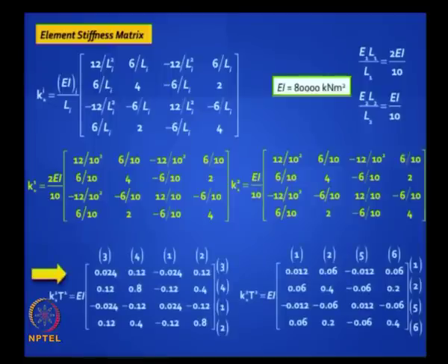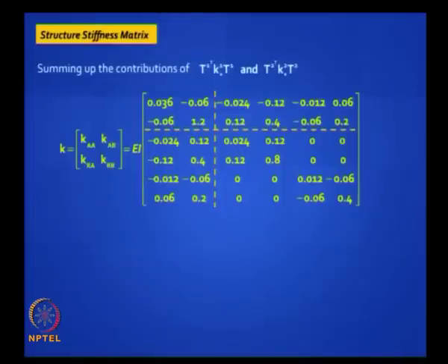Next, you pre-multiply or you post multiply the element stiffness matrix with the transformation matrix. Now you bring in the linking coordinates, okay. Actually the transformation matrix is identity, so there is no effort at all. I have just substituted the values of L here, that is all. So you get this, and then when you pre-multiply the whole thing with Ti transpose and you do the slotting business, you will get the full 6 by 6 matrix. Is it clear?